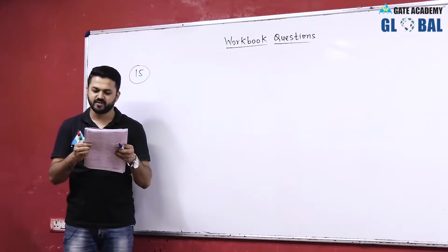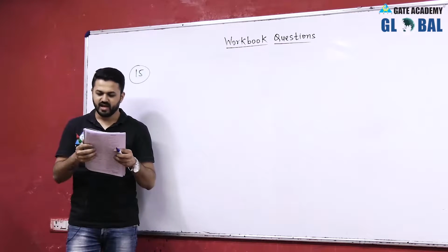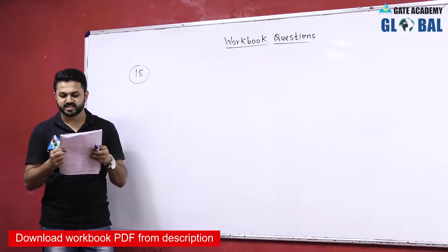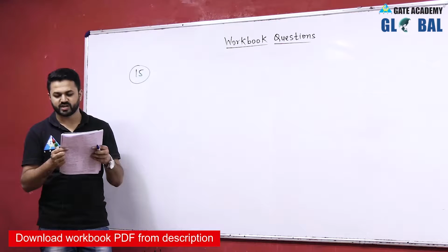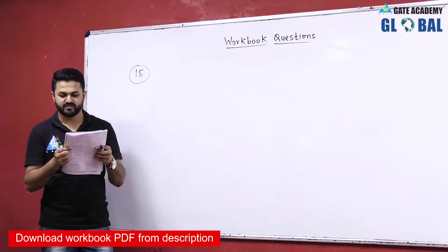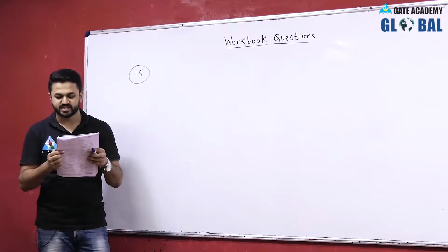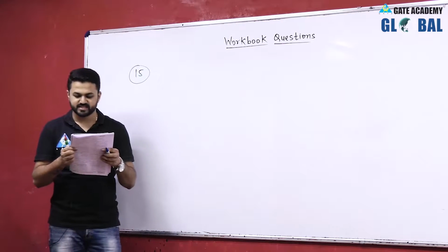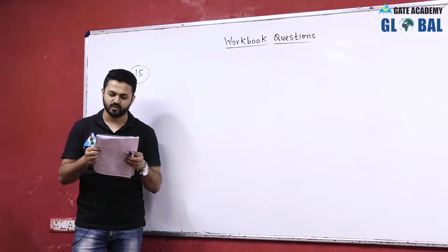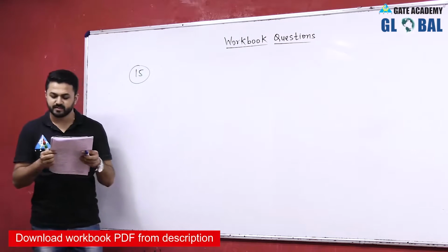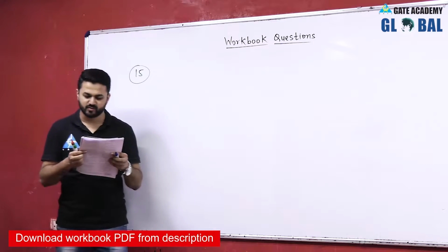So next is common data for question number 15 and 16. An amplitude modulated station transmits a power of 40 kilowatt and uses a modulation index of 0.707 for sine modulation. The antenna is represented by a 30 ohm resistive load. Question number 15 is the peak amplitude of the carrier before modulation, and question number 16 is the peak amplitude of the carrier after modulation.